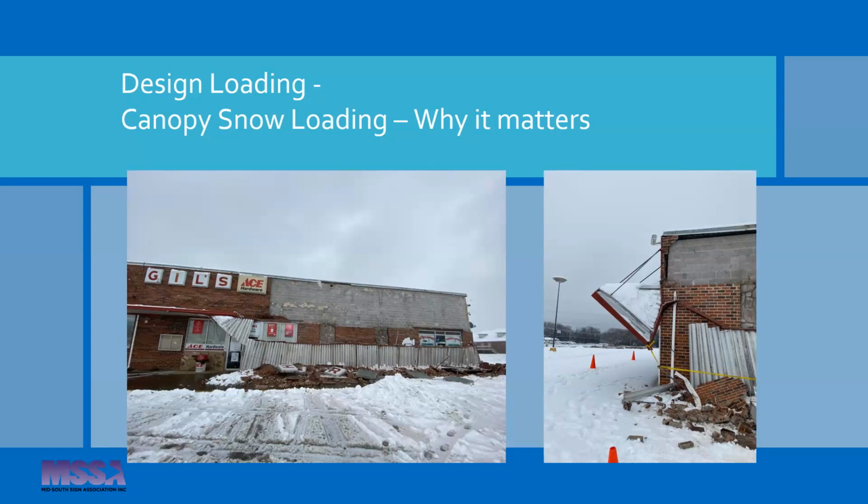And so when that wet snow came, hit those canopies, and started drifting up against the wall, not only did the canopy peel off the wall, it peeled the whole brick from there up off as well. Always remember, you've got to anchor these things into the block itself. Just into the brick is not sufficient for anything of significant weight.